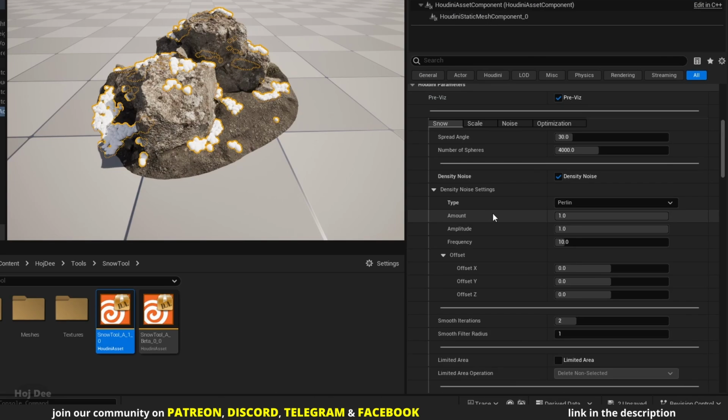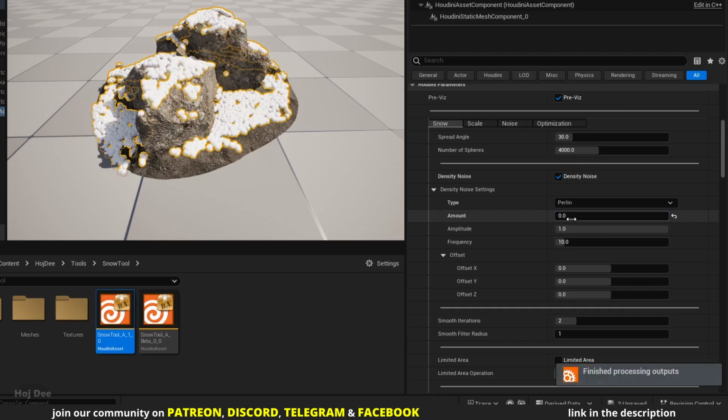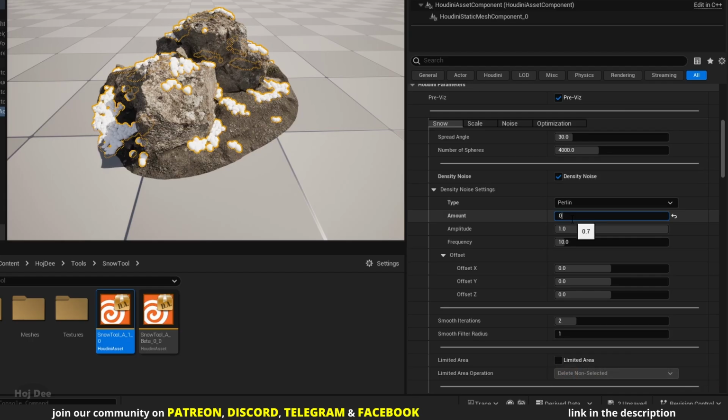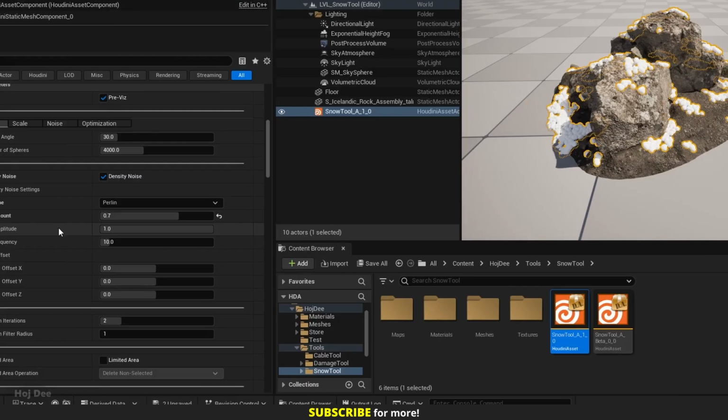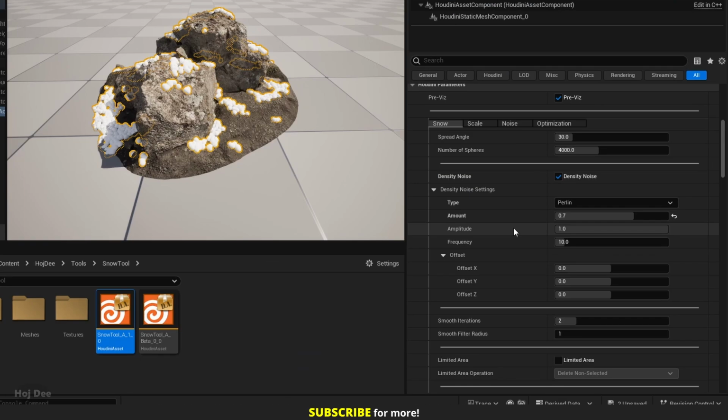Amount controls the effectiveness of the noise. When it's 1, it's fully effective, and when it's 0, it's like the density noise is off. We can tweak this value to see what looks good. Let's continue with 0.7. Amplitude controls the density and can even reverse it.